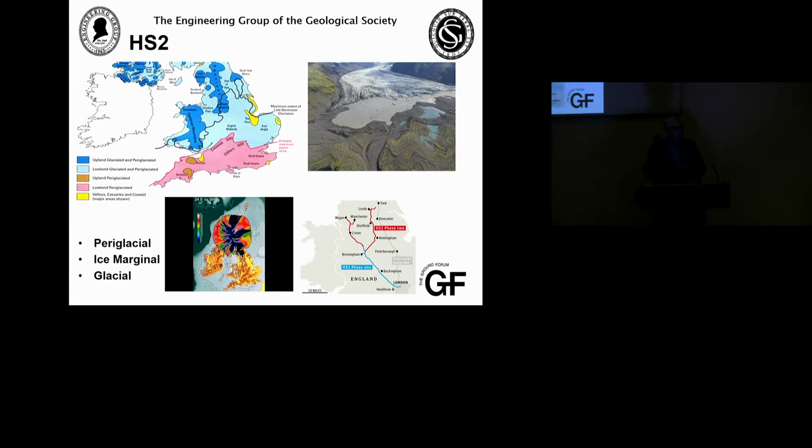So this is these climatic fluctuations, these Milankovitch cycles, these oscillations. Now, geotechnically, every time you see it explode and then retreat, that's the ground profile being modified. That's a new set of deposits being formed, a new groundwater regime in that particular environment. So we've got this extremely dynamic terrain that's then being generated by these climatic fluctuations. So it isn't a case of one move forward, one retreat back. We've got a very varied, very complicated legacy because of that ice sheet growth and that ice sheet decay.